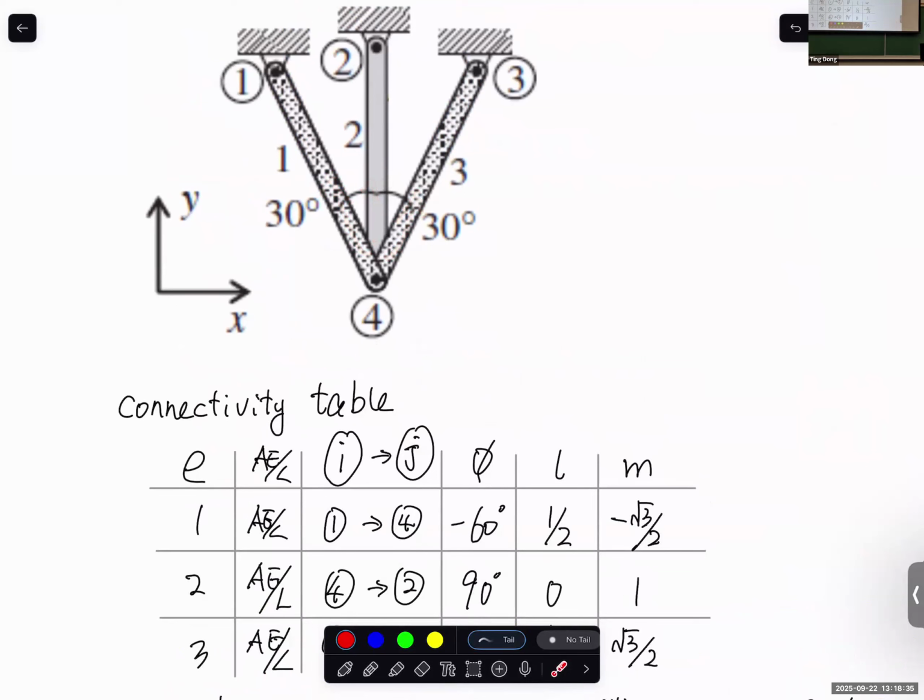But if you just imagine, let's say all 3 have expansion, and of course all 3 want to expand the same, since it is the same temperature increase, so they want the same elongation. But since the point is symmetric, they need to stay somehow in this way. The actual elongation in this element should be smaller than free expansion, right? So we cannot say that the force applied by node 4 to element 1 is 0. It's not 0. So also the force applied by node 4 to element 2 is not 0. Force applied by node 4 to element 3 is not 0.